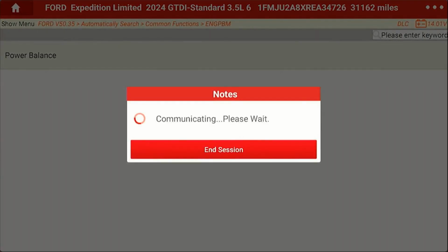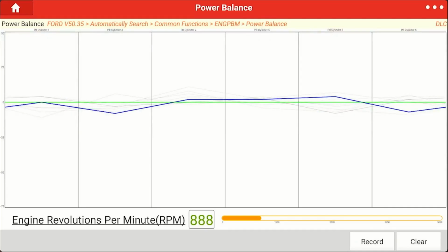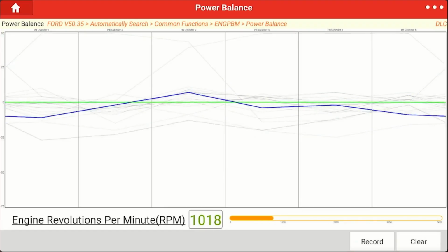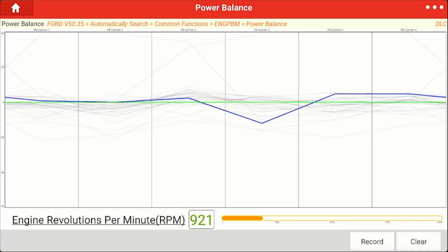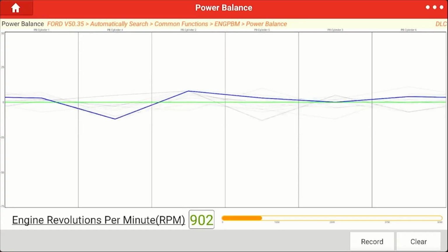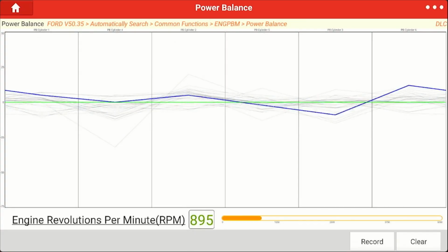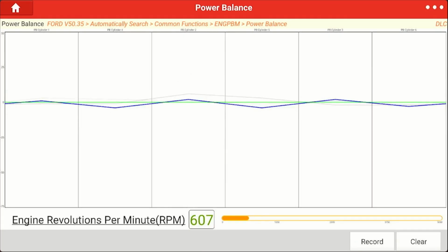If you notice, you've got a graph. This graph is clearable, okay? If you had a misfire in there, you'd of course see the one cylinder go ahead and show a problem. I just glitched the throttle so you can see what happens. Now, if you notice, this is a graph and we're looking at about 10 RPM. It looks like the graph moves up and down quite a bit, but it really doesn't. It's about a 10 RPM swing. They want it within that 25, so it's not a problem.